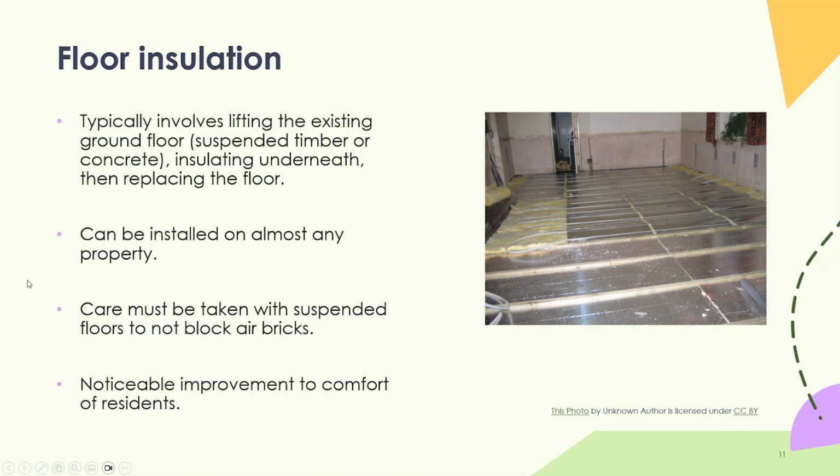You can also do this with concrete floors. So if you've got a concrete floor, typically in a rear extension of Victorian houses, it's a bit more of a disruptive job in the sense that if you've got a floor which hasn't got insulation underneath the actual concrete screed, you need to break that up, remove it, and then redo the floor. As I say there, it can be installed in most properties.